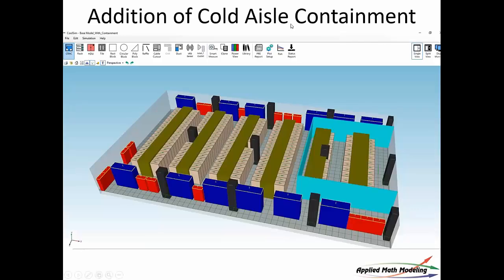This is just cold aisle containment, not too complicated here. All you need to do is put the containment in place. I want to remind CoolSim users that on the containment side, it's not necessary to make small pieces of the containment. You can take one long piece of containment and slice right through the racks, and then do another one on the other side, put the top and the ends on it, and then group it, and then clone it. Clone is copy with offset. I often see people trying to make little small pieces to contain, and you don't need to do that.